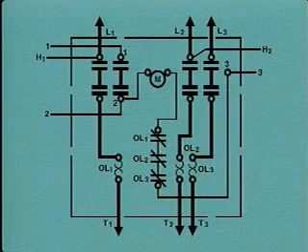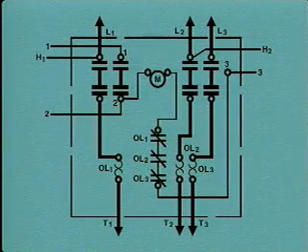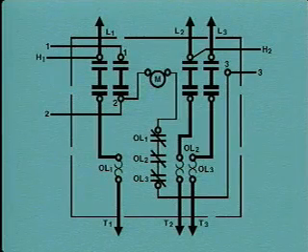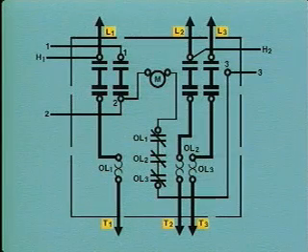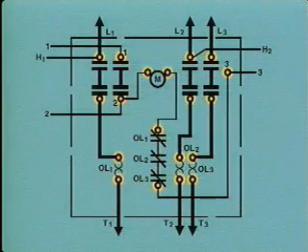In this example, the fuses and the step-down transformer are located outside of the controller's physical enclosure, so they do not appear on the wiring diagram. The line leads and the motor leads are labeled the same way on the wiring diagram that they are on the schematic diagram. However, on the wiring diagram, the electrical connection points are indicated by circles instead of dots.